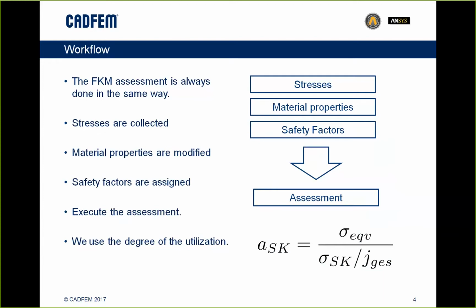The sample will be polished. My real part might be polished. Usually it's not because it's too expensive. And also my real part might be much, much bigger than my small sample. When I have a small sample, I can produce that really well, especially when I make some kind of heat treatment. I can control the heat on a 1 centimeter part pretty accurately.